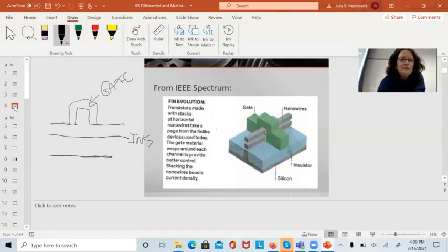And putting that insulating layer there meant that we couldn't get electrons from the bulk coming up and interfering with our transistor action. So both of these things together made transistors so much more ideal that even though it's more expensive to do the processing, people bought this because it makes better circuits. Their output resistance gets better. All kinds of things improve greatly.